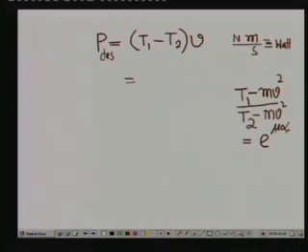Now, which alpha should you take, for the larger pulley or for the smaller pulley? Now, you understand, if the pulley materials are the same, and of course the same belt is running, then the product of mu into alpha will be lower for which one? For the smaller pulley.